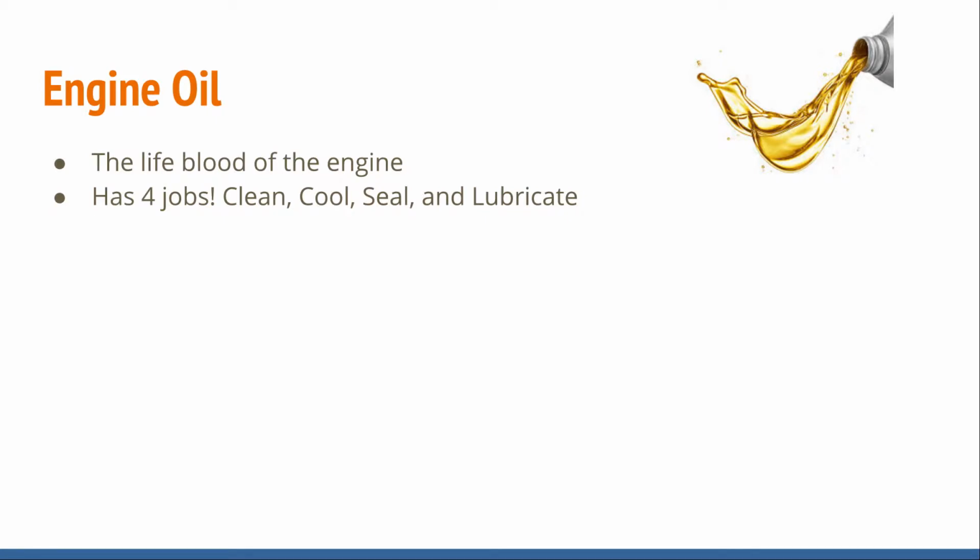Cool. Engine oil actually cools parts as it passes through as well. Some engines use an engine oil cooler. Usually, most don't, but the engine oil just rotating through the engine does cool it down. The engine relies on that cooling, and engine oil actually helps seal, which sounds kind of odd, but your piston rings that we talked about earlier would not seal near as well without oil.